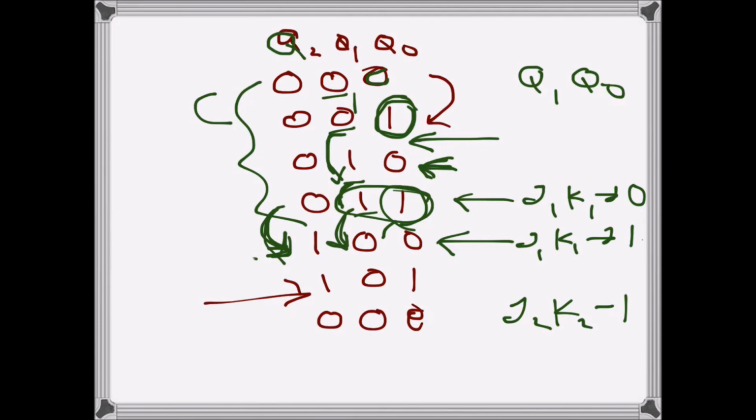So that's there. But this is just the operation of an up counter, and if we leave it like that, it will work as a 3-bit up counter, so it will count up to 7, 0 to 7. But we want it to count up to 5 and then go to 0. So for 6 clock pulses it should count. So now comes the clear function of the clear input.